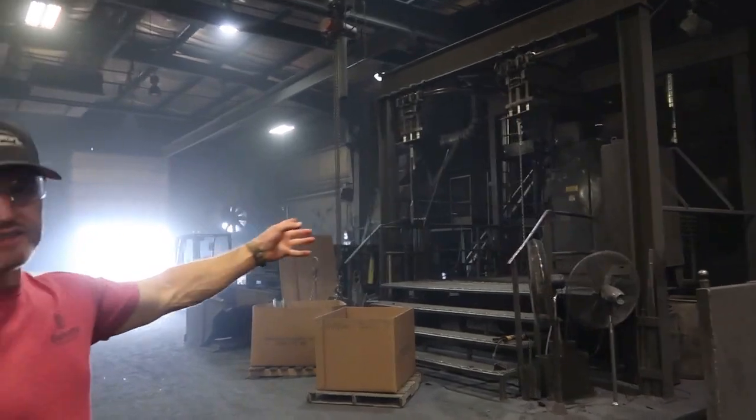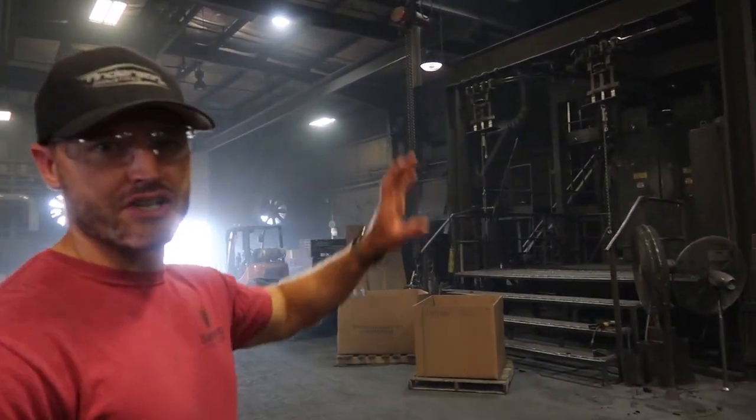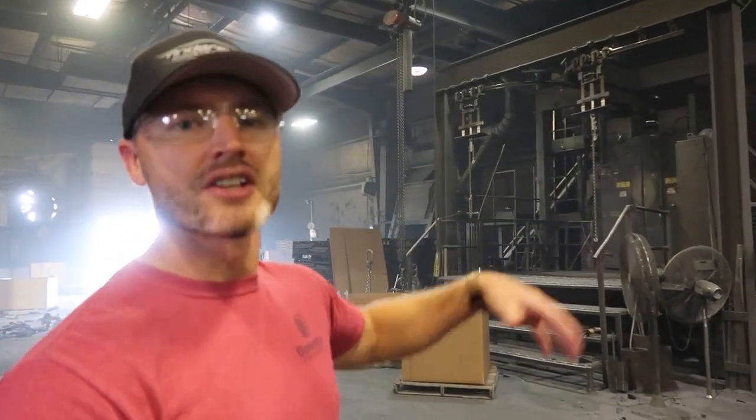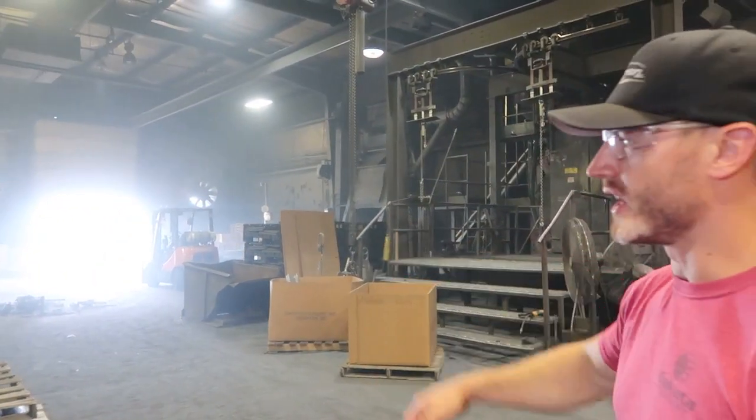This is our cleaning department, so all the castings get taken out from our pouring floor, and then they move up into our cleaning department. We first run them through a steel shot blaster, either a cabinet or a wheel abrasive style. So that's our large cabinet blaster where we just hang the castings, put them in, steel shot blast them, and then they go into the cleaning area.